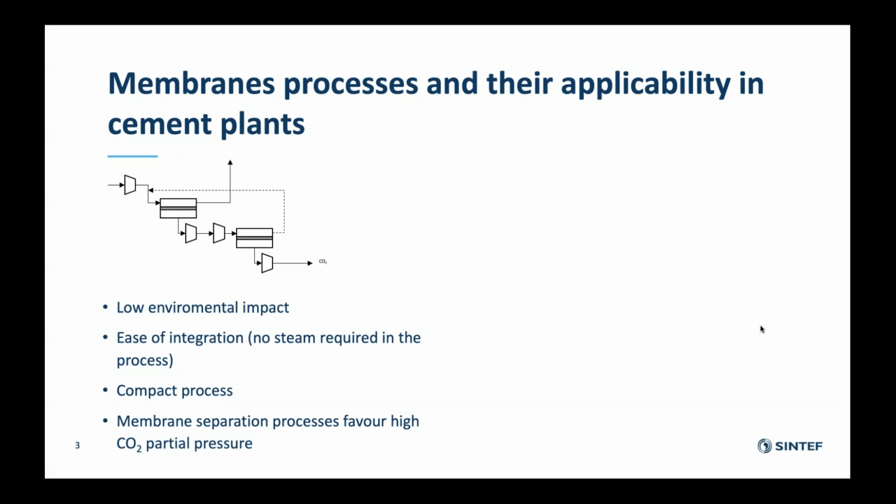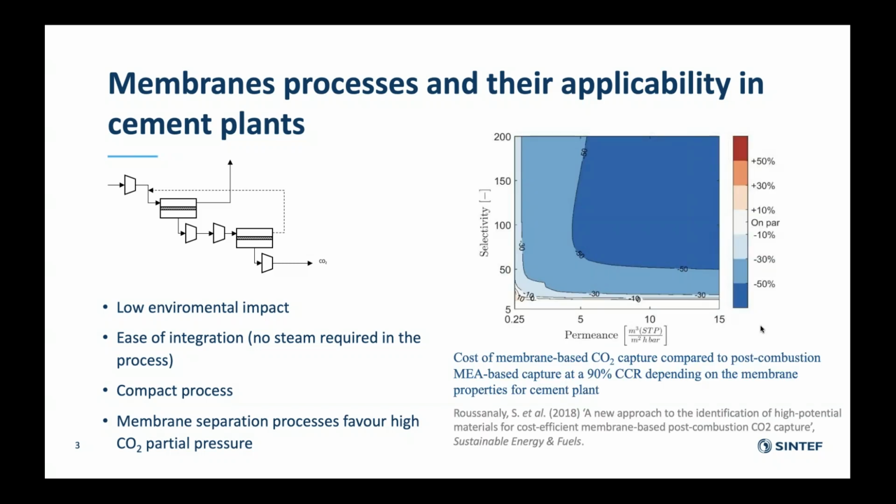Additionally, as I mentioned earlier, because of the high CO2 concentration, and because for membranes the driving force is the partial pressure differential, it is very attractive here with CO2 concentrations of 22%. Earlier work that we did in the NCCS and BIGCCS projects, we have seen that membranes are very attractive for these kind of compositions.